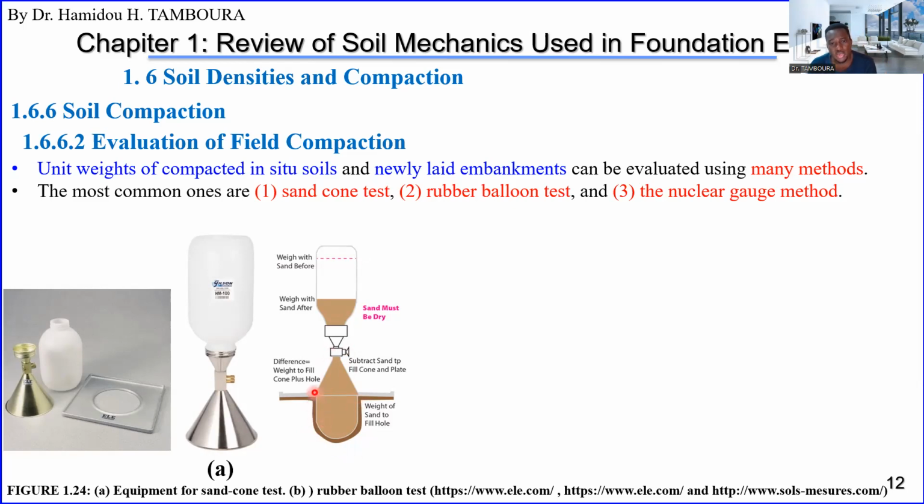Okay? Here, it will give us, because we know the initial volume. Here is the weight before the sand, and here is after. Maybe the level was here, and all this part went in the hole. So by doing that, we will know the volume of the hole.